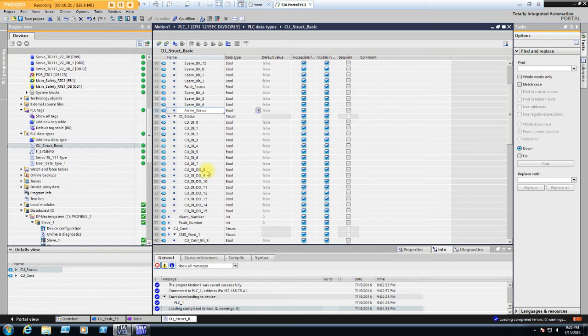Yeah, the default way the drive sets this up, it actually flips the bytes so they're backwards in the drive, so they show up in the PLC this way, which is more intuitive. So it's just another little gotcha. Just be careful about that and double check that you set the drive up that way, and that this matches the way they come from the drive.